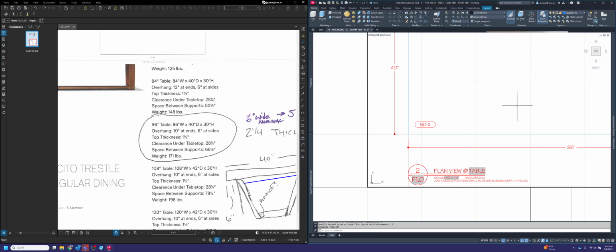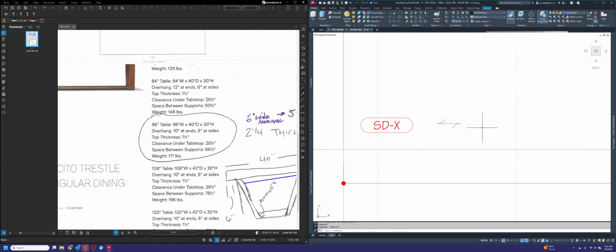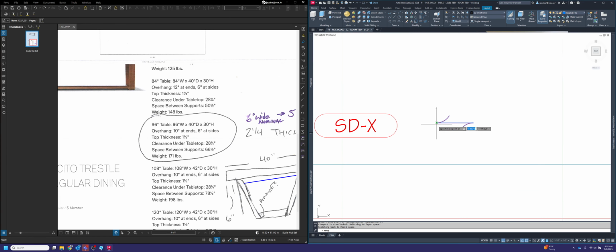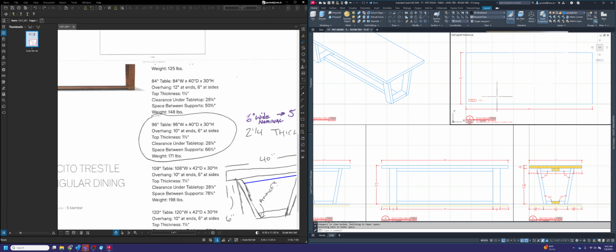Whenever you're dealing with solid, veneer, and sometimes laminate, you'll have grain directions too. So always take note of that. Anytime there is a grain direction on a material, you want to make sure that it is shown on the print. If we forget that grain direction, then it leaves it up to the architect to determine what that grain direction is. And sometimes they may pick something that's a little silly.